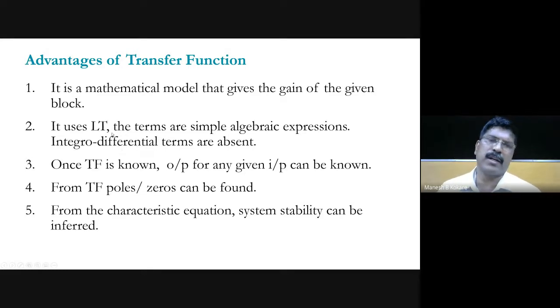So in a transfer function, you will get only simple algebraic equations instead of integral differential equations in the time domain, right? Then third advantage is that once the transfer function is known, the output for any input can be found, so you can determine the output for a given input if you know the transfer function. So that is the third advantage of the transfer function.